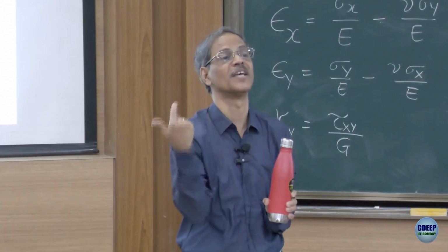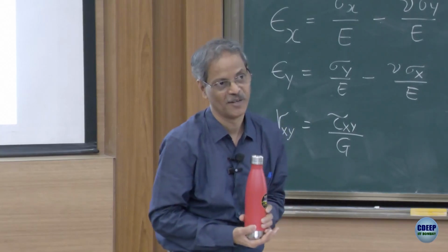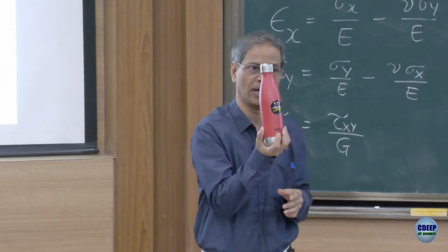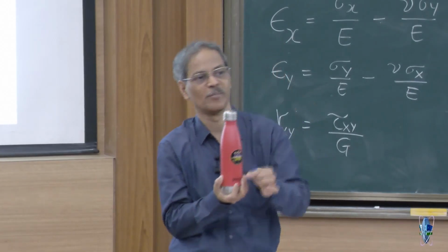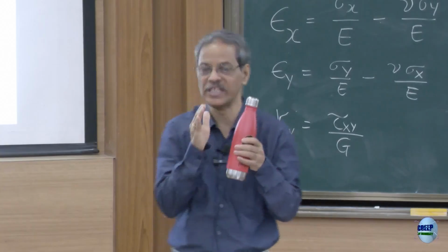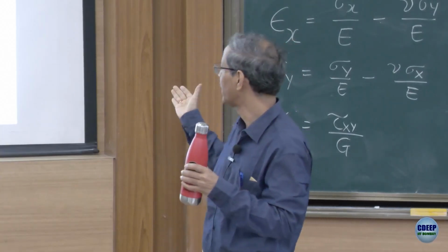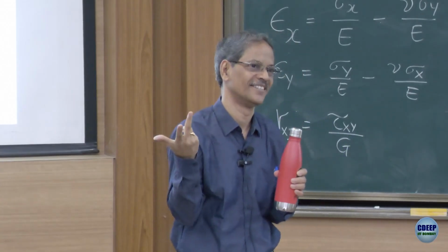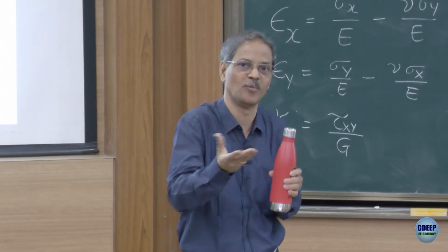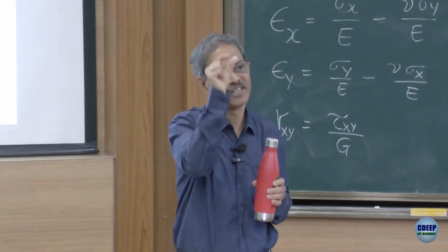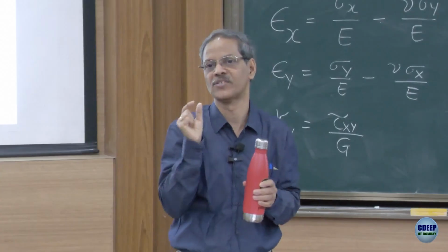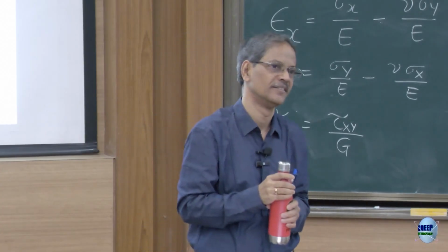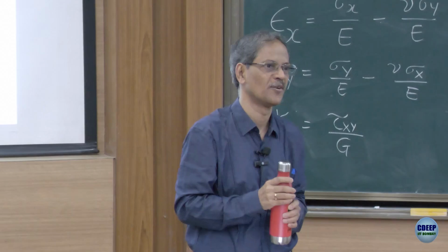Everywhere else it will be the same thing. So again, from a three-dimensional problem, I can bring it down to two dimensions. The two dimensions here will be the radial plane and the axial plane. Theta has been knocked out. So my finite element domain to be modeled will only be this piece, which is in the r and z coordinates. Is that making sense?